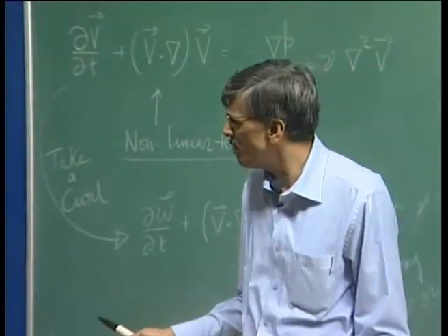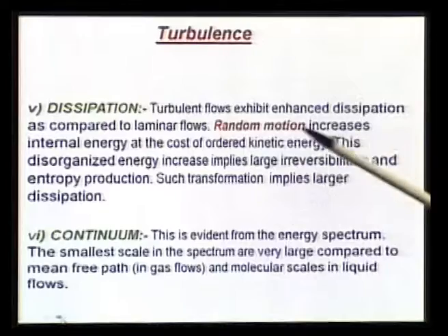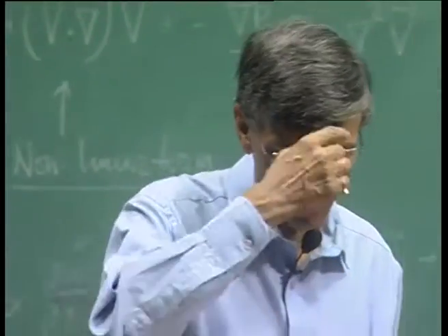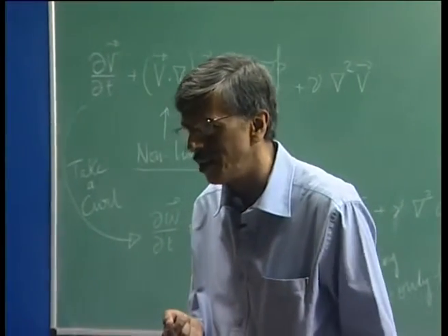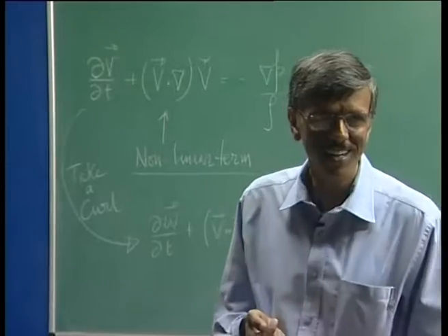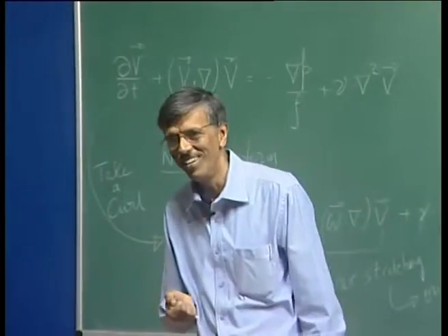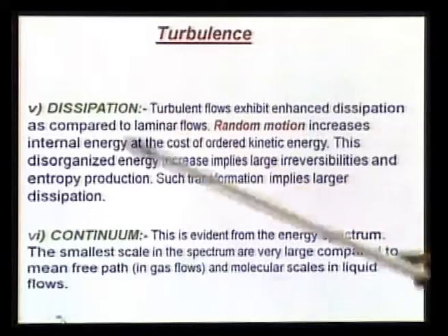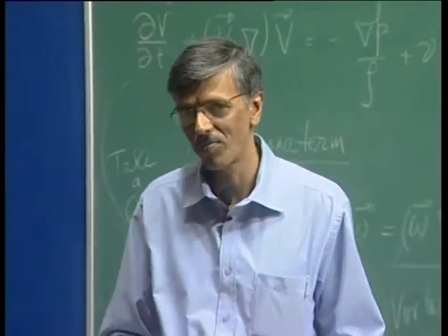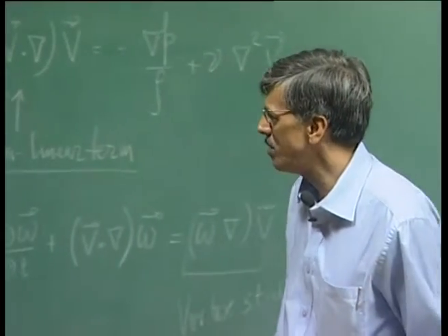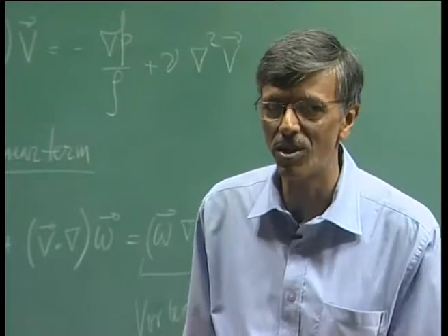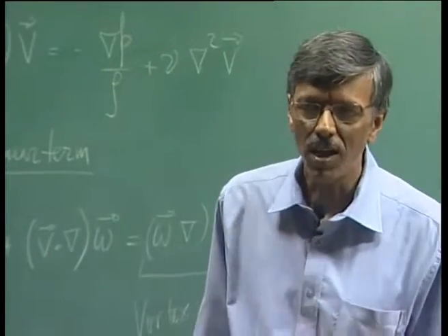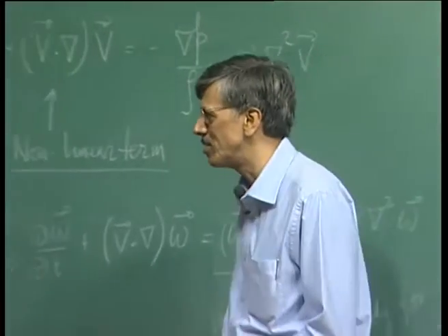Now, this is a phenomenological observation. The turbulent flows are more dissipative. You ask an airline operator, they will complain till their face turns blue that they spend all the money because the flow is turbulent. They would love to have laminar flow. That is because we have very high dissipation in turbulent flows. Okay? We have very high dissipation, and that is not very unusual for us to understand. We already have talked about diffusivity. If I have larger diffusivity, I will have larger dissipation. So, that is okay.